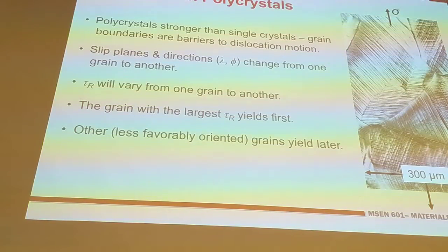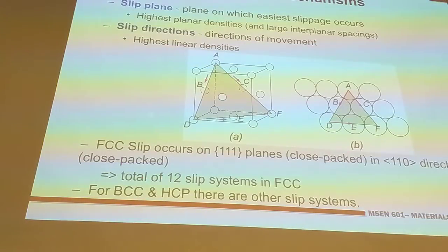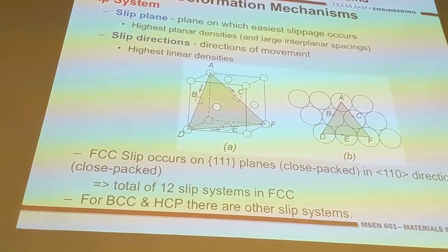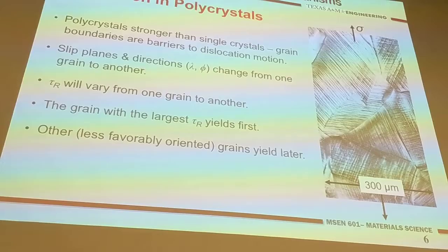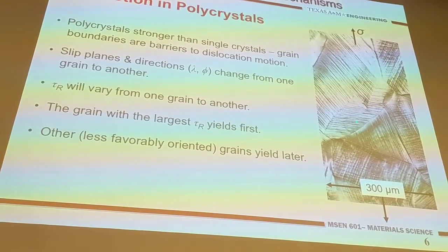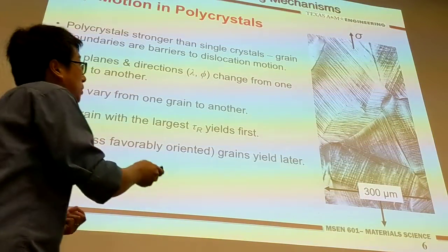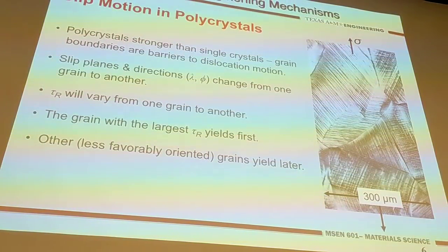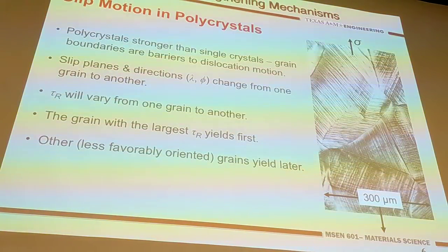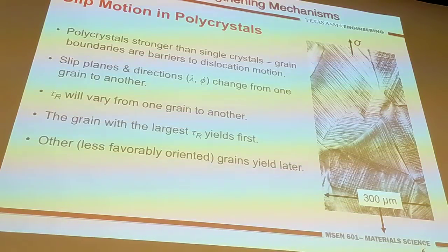Okay, we said in the previous case that if you want to deform the crystal, you need to think about the different slip system of each grain, depending on specific orientation. Therefore, if you want to deform a polycrystalline system instead of a single crystal, you macroscopically apply the stress, for example tensile stress here, but microscopically you consider the different orientation in each grain.